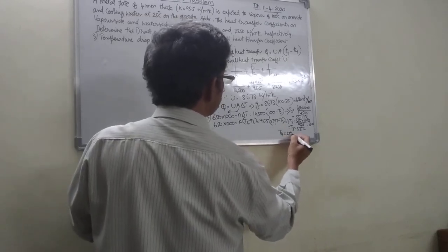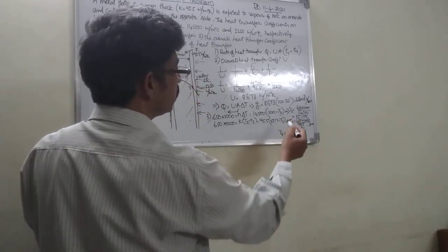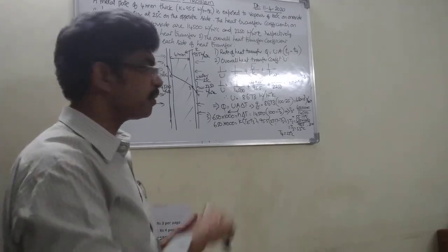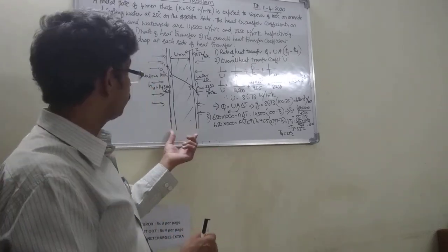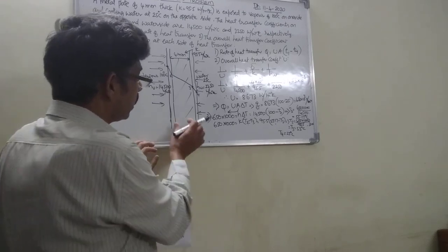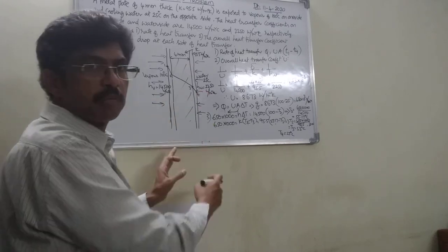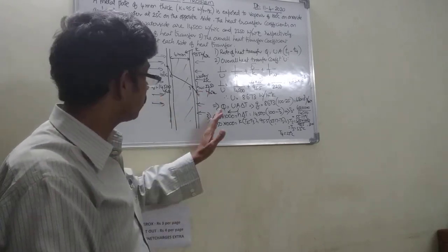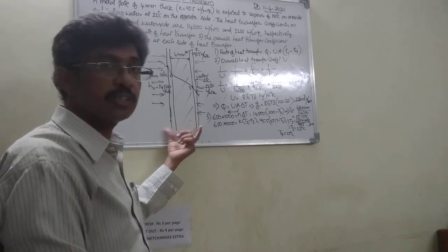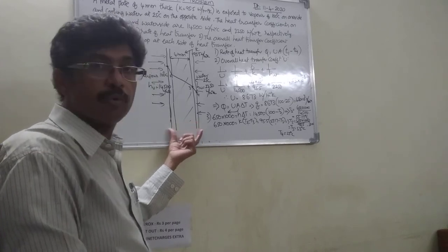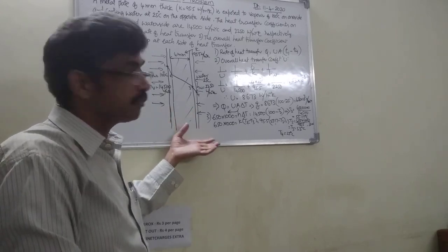So now we have all the temperatures, that is T1, T2, T3 and T4. This way we can solve the problem of heat transfer within a conductive plate surrounded by convection atmosphere, like one side vapor and one side water. So if a solid conductive material is surrounded by convective substances, then it's a problem of conduction plus convection.